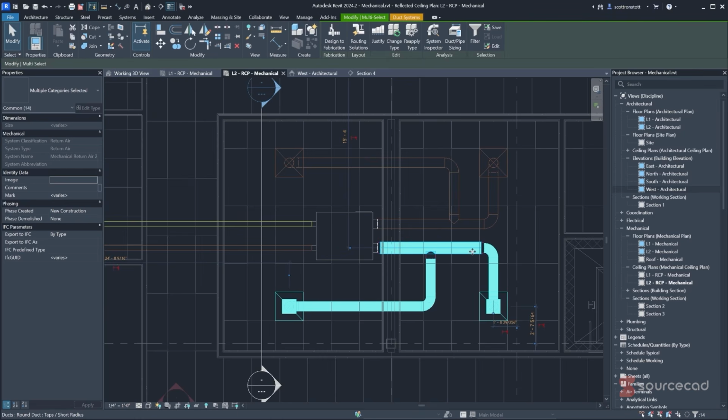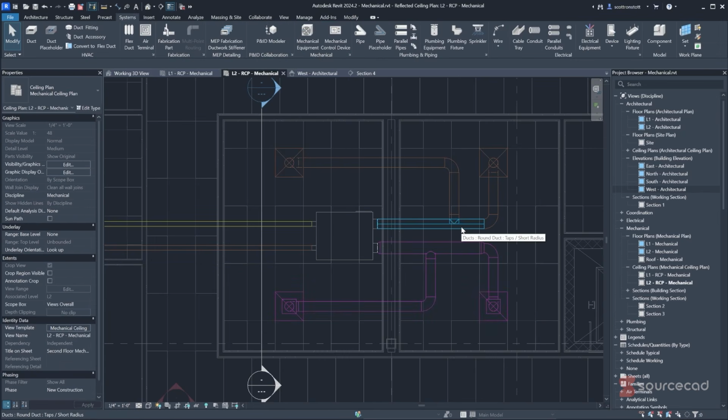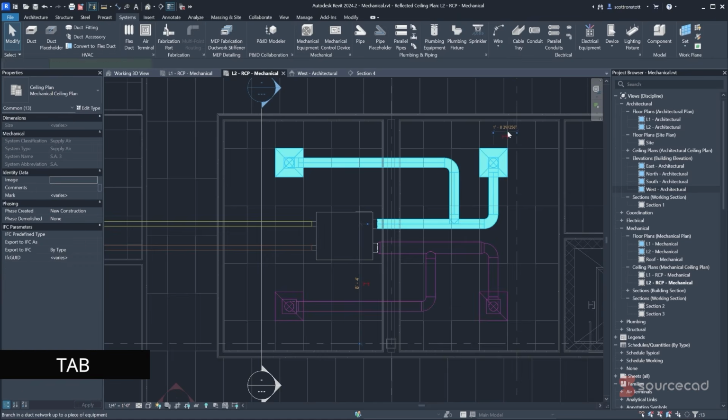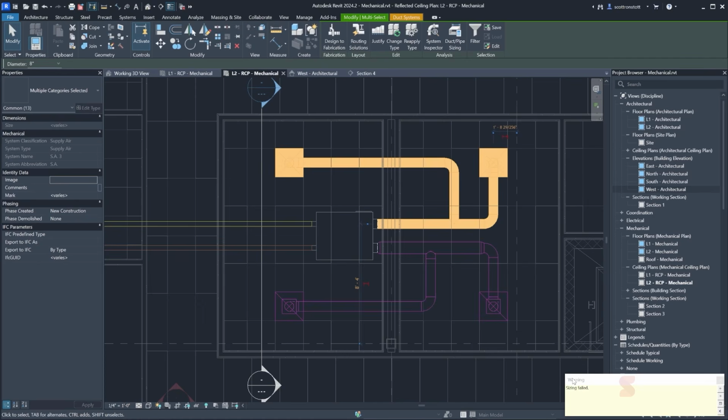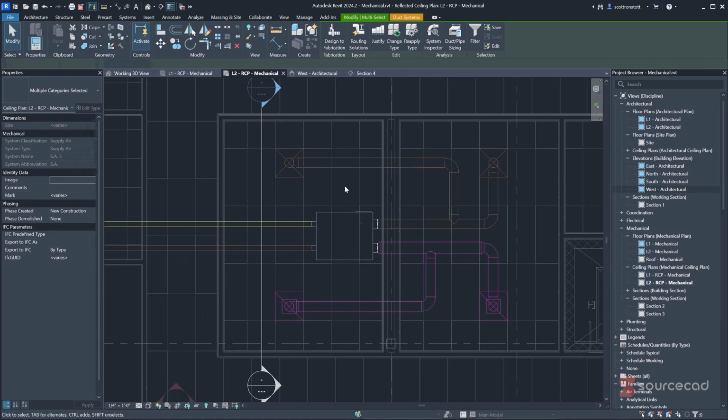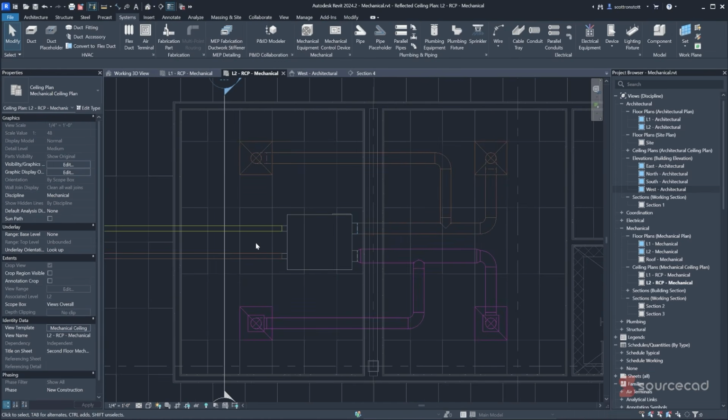It made it a little larger because it determined that we needed a slightly larger duct to have equal friction throughout the system. So over here, I'll do the same thing. I'll press the tab key a couple of times until everything highlights and then click, and then run the duct pipe sizing tool on it with equal friction. And it says sizing failed. Well, there's nothing there to fail really. I'm not sure why it did that.